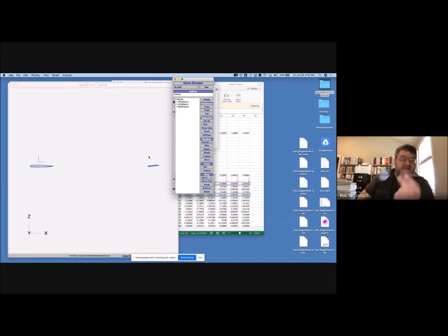And I used to do this demo in class. I don't have a piece of foam board here. I've got some cardboard, so I might be crazy enough to do it. But if you take a piece of 2-inch insulating foam that you would have on the side of a house, and you take a dart and throw it backwards, standing a normal dartboard distance away, your dart will flip over midair and will go into the foam correctly. And that's because it is stable. It is so stable that if you throw it backwards, it's going to correct itself.